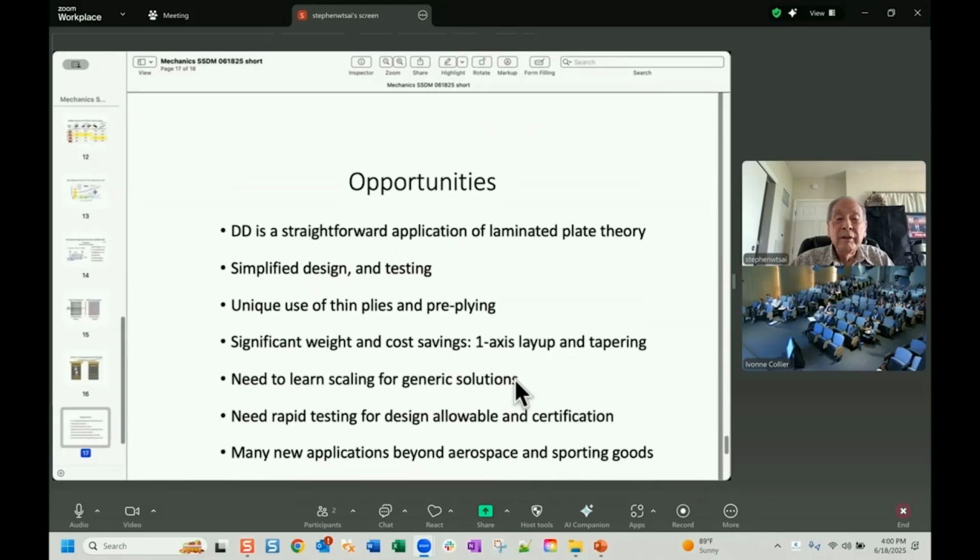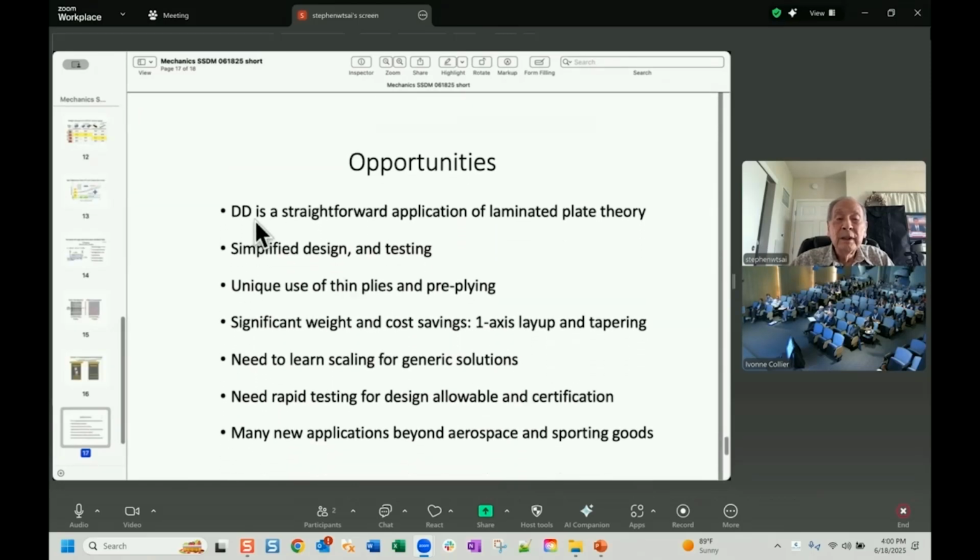And therefore, for composites, double is straightforward, it's the same laminate plate theory, and all the data between quad and matching double are either equal or double is a little higher than the quad. And it makes simplified testing much easier because you can scale. That shows a difference.